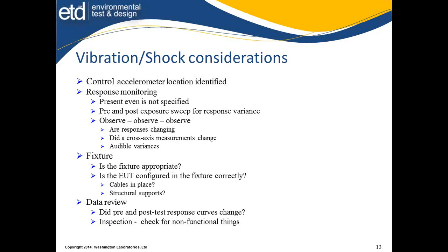Data review, look at it. Just analyze the data and examine it. A pre and post-test response curve, did things change? Inspect, check for non-functional things like breakage, cracks, looseness, rattles, things of this nature. It's not just a saying, is it operating?